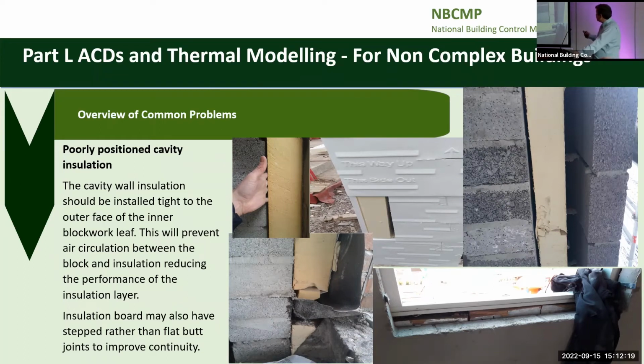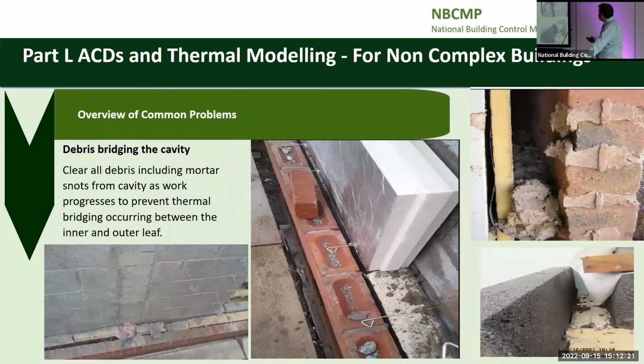I think a picture would help in one of them. Debris creating bridges in your blockwork, and then maybe overuse of wall ties that you may not have accounted for. The locations of cavity barriers, and dirty things, and you can see it here as well. Mortar drop down here. And who's going to close off this little bit? Do you know?